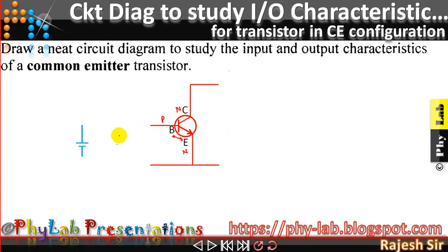Here you can see I've drawn the positive of the battery. For the CB junction in reverse bias mode, the collector of this transistor happens to be N. So I am going to connect the collector to the positive of the battery, so that N connected with the positive of a DC power supply makes it a reverse biased mode. This is how I'm going to connect the battery.